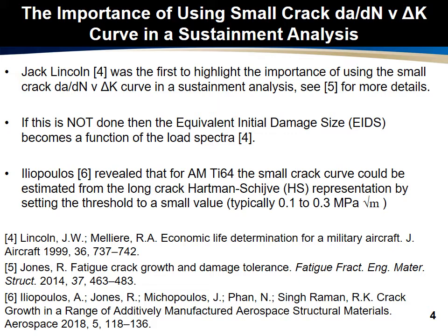It is now known that for additively manufactured Ti-6-4, the small crack growth curve can be estimated from the long crack growth Hartman-Schwalbe equation representation by setting the threshold term to a small value, typically between 0.1 to 0.3 MPa root meter.